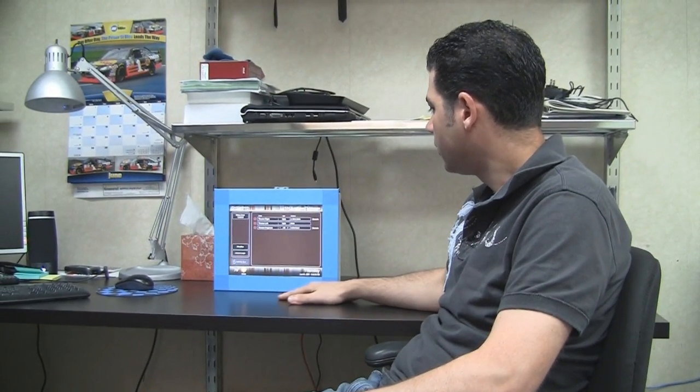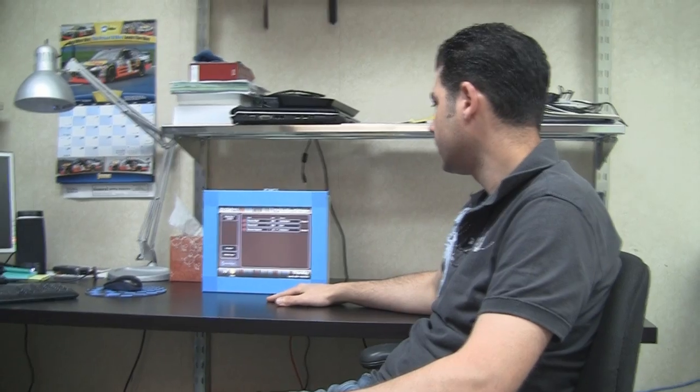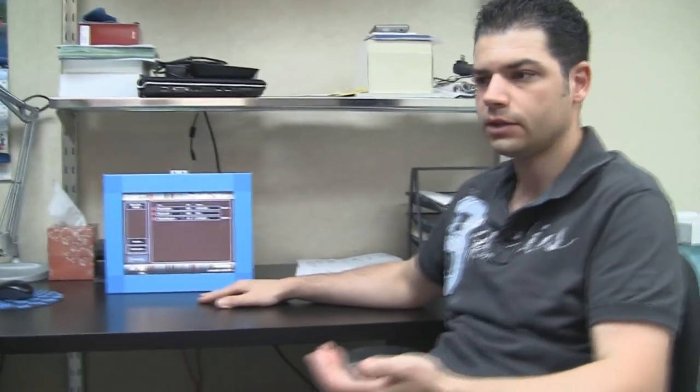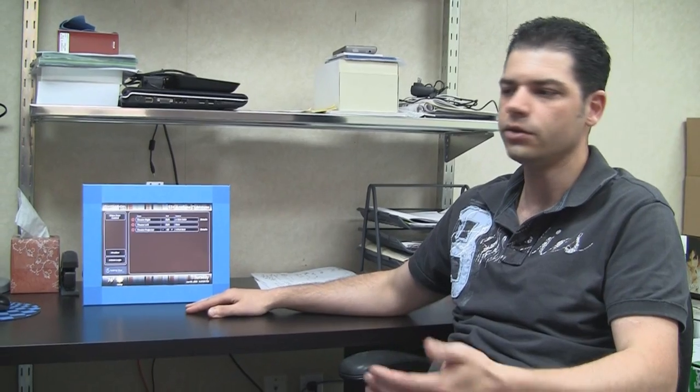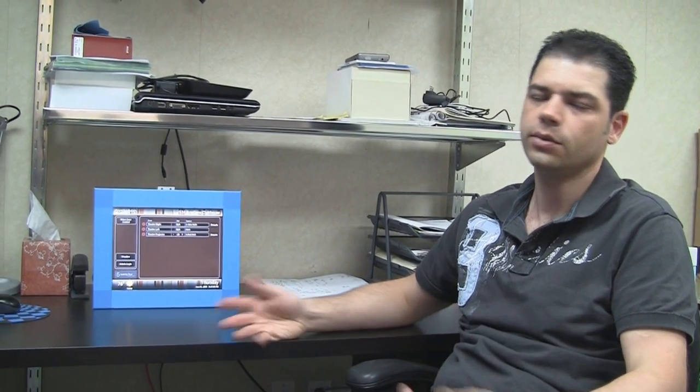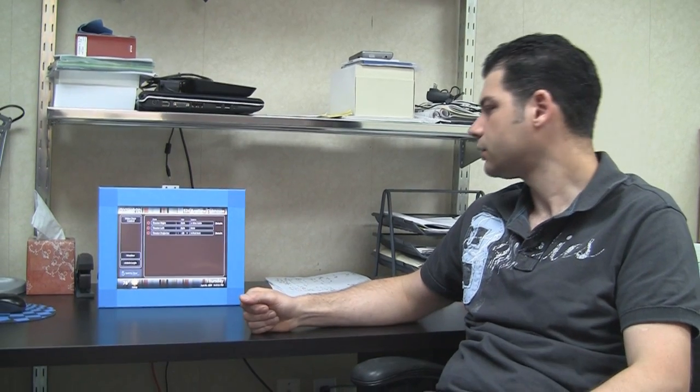So another feature that I implemented was with the projector zone, and even with the TV zones, when I select an audio-only source, I don't want the TV to turn on, and if it's on, I want to turn it off. The reason for that is there'll be no video going into that TV, so it'll just be showing a black screen. So what's the point of having the TV on?